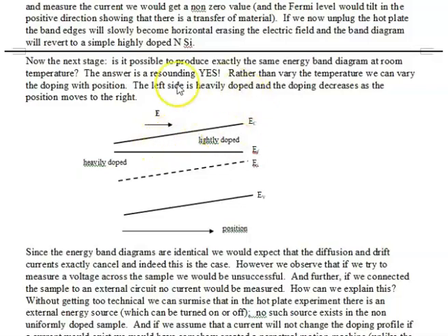So if I have this as the base region in a PNP type structure, and I have holes coming in from the emitter, which is over here, they're going to find themselves in a region where they feel an electric field. So not only is there going to be a diffusion component, there's going to be a relatively healthy drift component, which will accelerate them, and that will improve the device performance of a bipolar junction transistor.